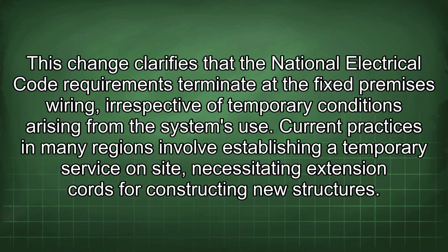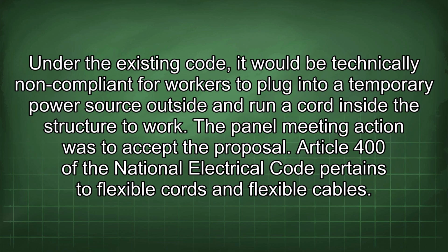Current practices in many regions involve establishing a temporary service on-site, necessitating extension cords for constructing new structures. Under the existing code, it would be technically non-compliant for workers to plug into a temporary power source outside and run a cord inside the structure to work. The panel meeting action was to accept the proposal.